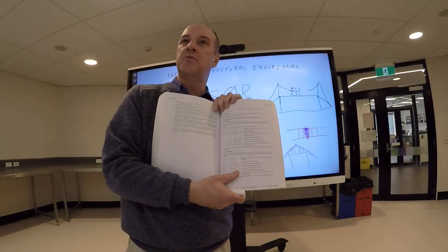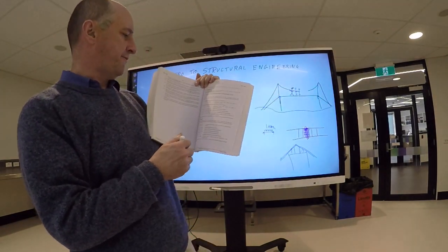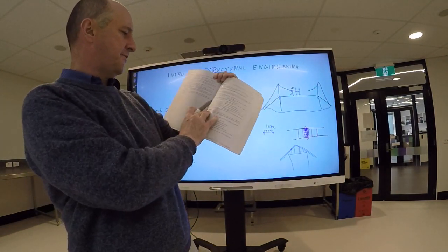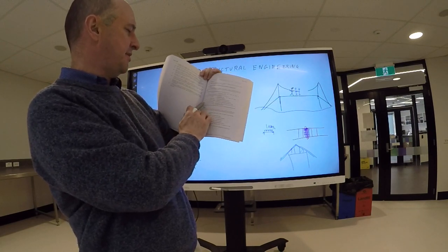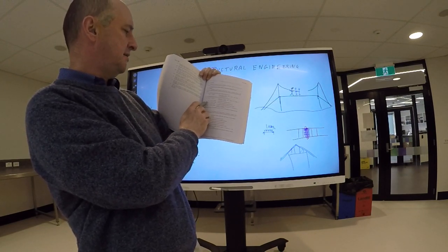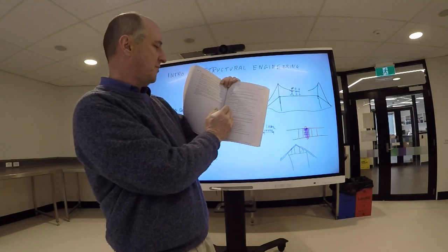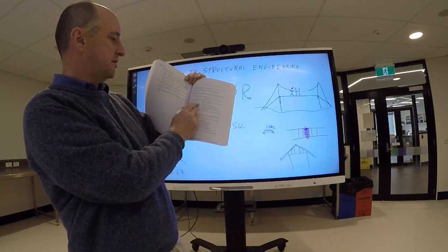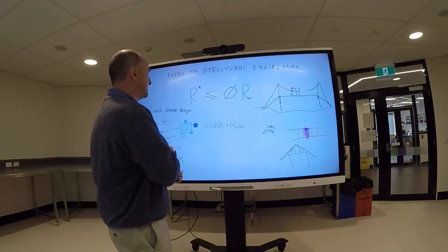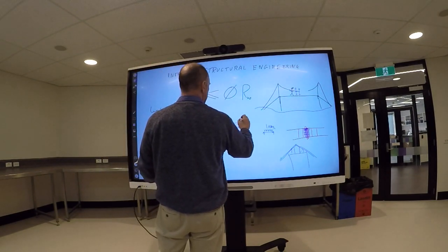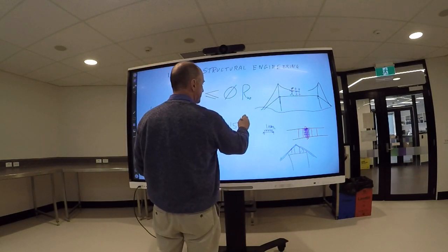If you go to 1170.0, in section 4, it says for combinations that produce a destabilizing effect, the effect, E, is 1.2 G and 1.5 Q. Dead load is often written G, and live load is often written Q.